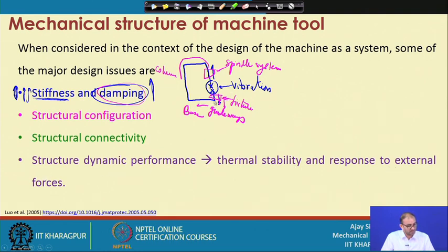External forces, that means, suddenly you are starting a machining operation. Consider that your workpiece is located here and your tool is here at this location, and the tool has to move from one location to this location to start the machining, right. So, when it is moving here, it is called dry run or the air run.